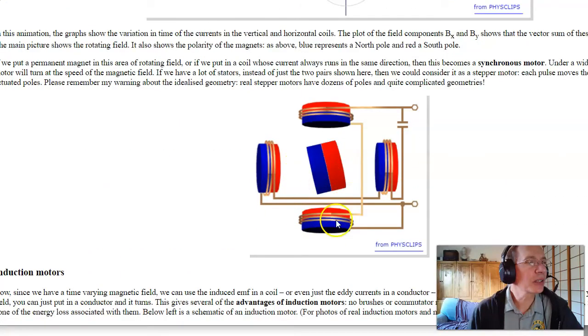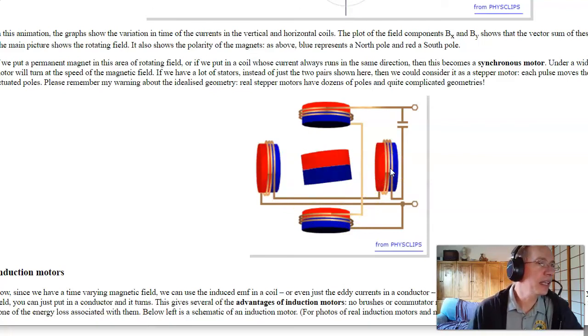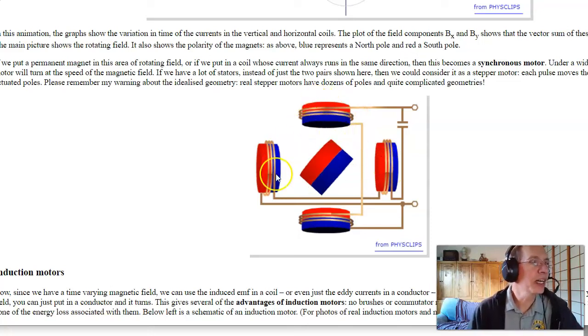So that's actually how a stepper motor works. I've got cosine on one axis, sine on the other axis. As the field rotates, the motor spins and follows the rotating field. If you make this a sine wave, I get a nice smooth rotation. If I step it, apply x is 1, then y is 1, x is minus 1, y is minus 1, I get a stepper motor. But really, stepper motors are actually two-phase AC synchronous motors.